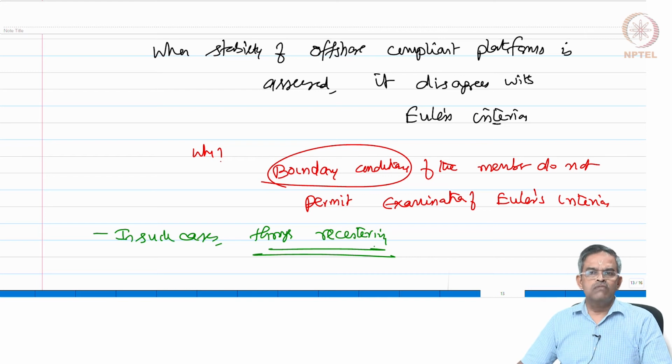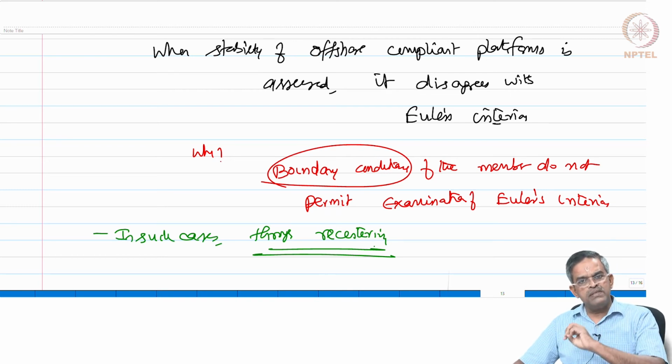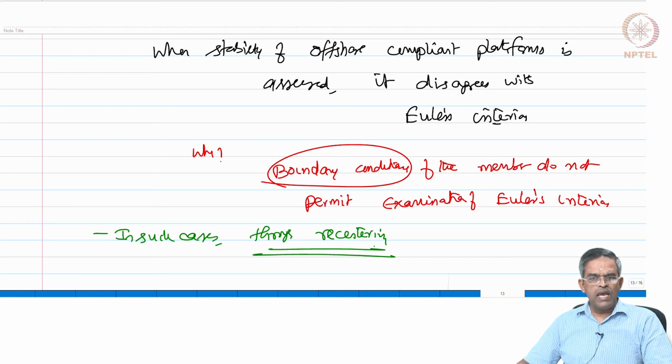It is well understood, well established, it is very well clear that the load capacity of a disturbed geometric form will be far lesser than the original load capacity. There is no question about that. The disturbed geometric form can always carry only a lesser load than its original geometric form, which is initially straight, perfectly elastic, etc. But what we want to emphasize here is, if that load capacity at the changed geometric form is PCR, we call that a stable condition.